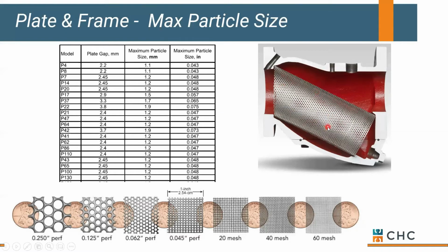but the way to protect it is to order a Y strainer with a proper mesh size. And obviously you'd want to be a little bit smaller than the max particle size. So make sure that's on your radar. We see a lot of installs where people are seeing a 50-pound pressure drop across their newly installed heat exchanger. Well, that means there's a lot of garbage in it.